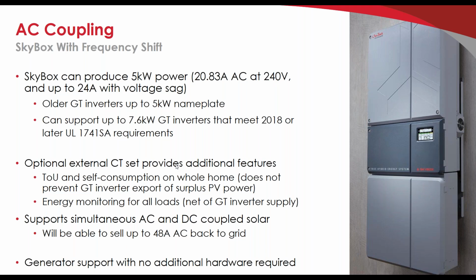Kale asks, maybe a different way, can we back up more than 5 kW by paralleling 2 or more SkyBoxes? Yes, you absolutely can. Again, that's separate from AC coupling today. The way to support stacking multiple SkyBoxes today is to not AC couple them.